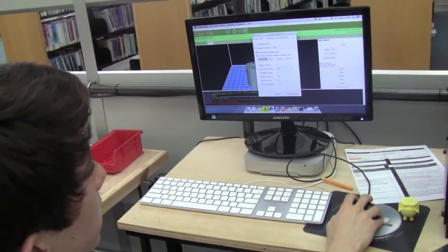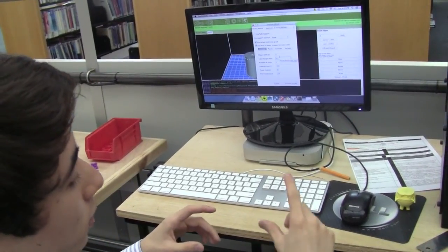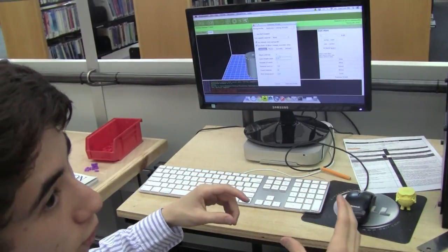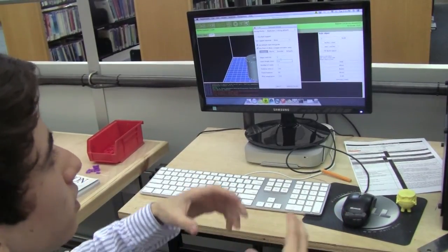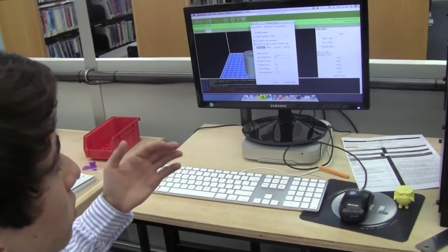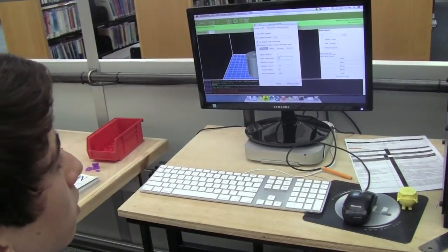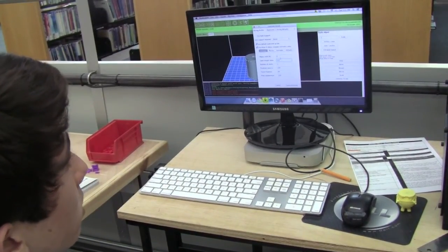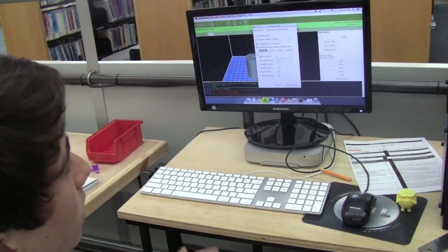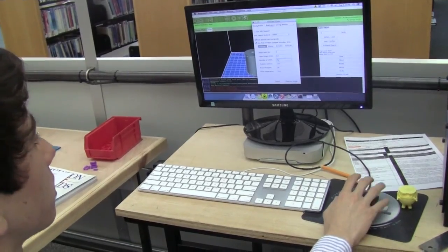This also affects print time a lot. Let's say you have 0.1 millimeter layers. If you have 0.2 millimeter layers, it'll take two 0.1 millimeter layers to make up one 0.2 millimeter layer. Sorry, I'm using too many numbers in there. So it would be essentially twice the print time, because there's twice the amount of layers. There are 2 layers for each one, so it takes a lot longer to print. But it is very nice quality, so if you want something to look good, it's actually worth the time in some cases, but it's really up to you. So just keep that in mind.